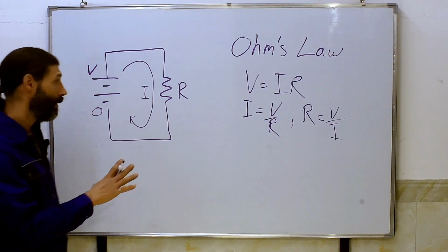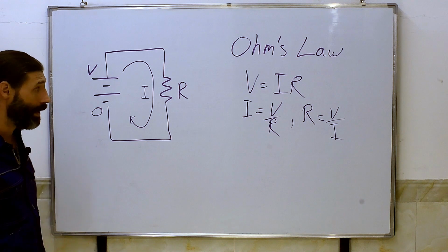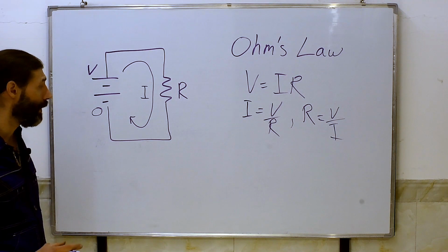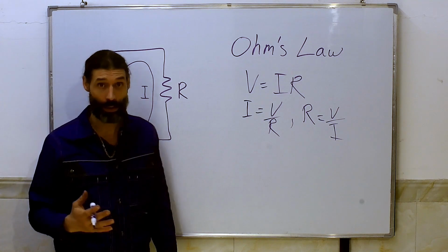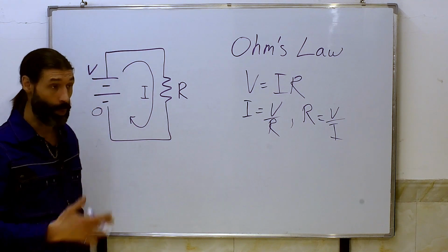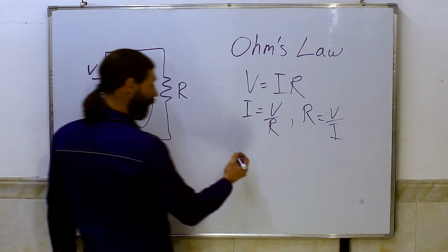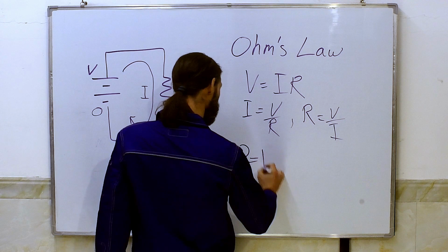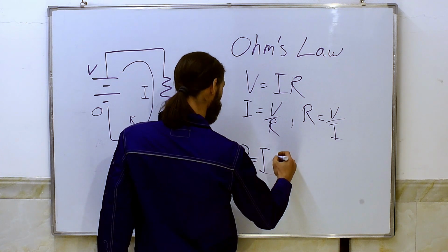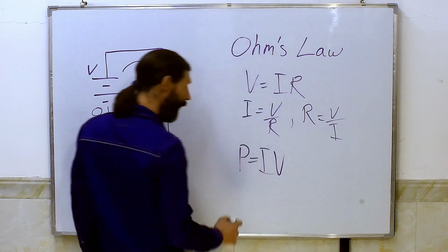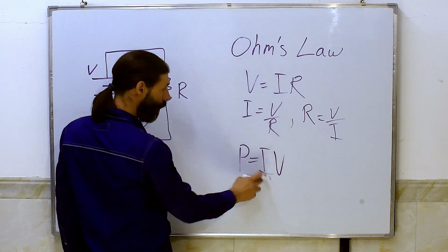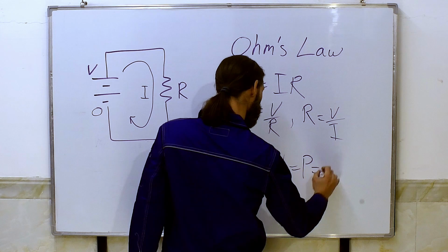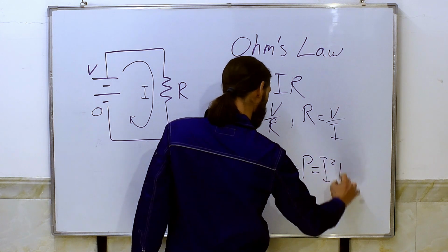Now that's going to do most of the heavy lifting in our calculations. Just one more calculation that follows from the definition of a volt and an amp, and we saw that in a watt. It is that power is equal to I times V. Sometimes we substitute Ohm's law into here, and we get power is equal to I squared R. But it's the same thing.